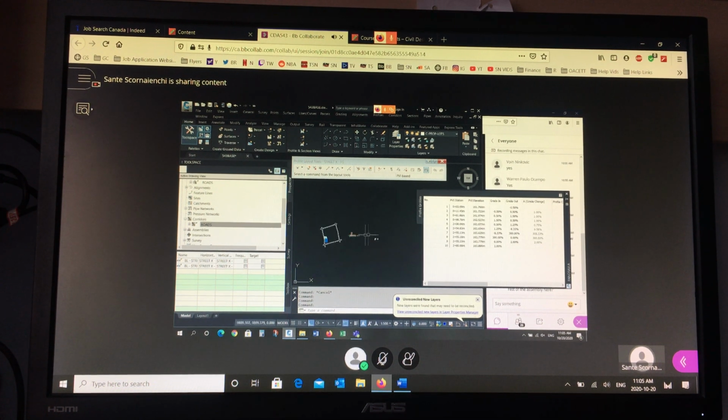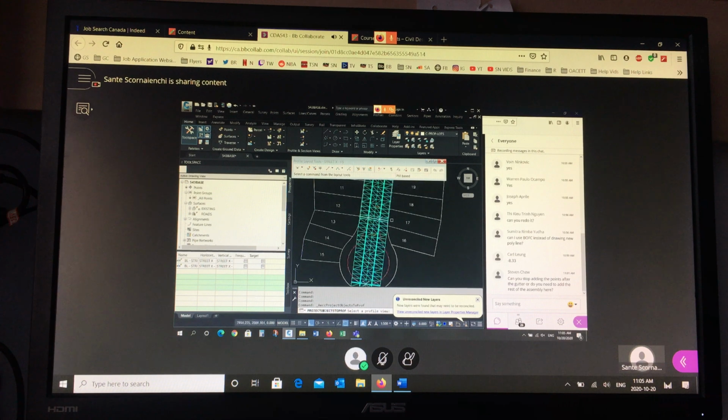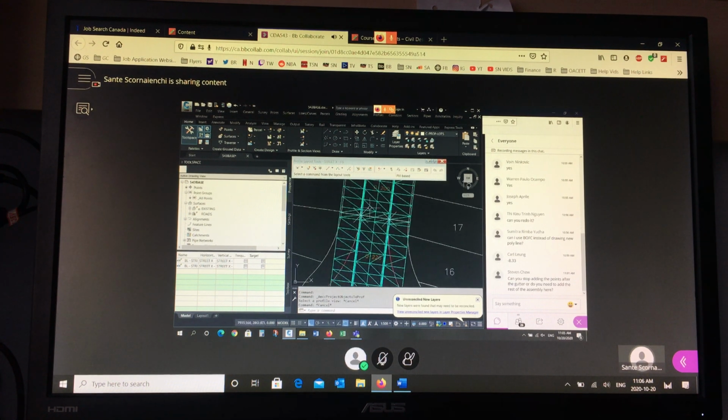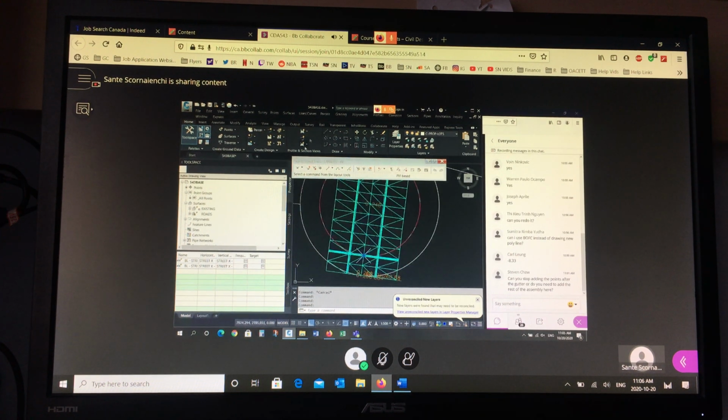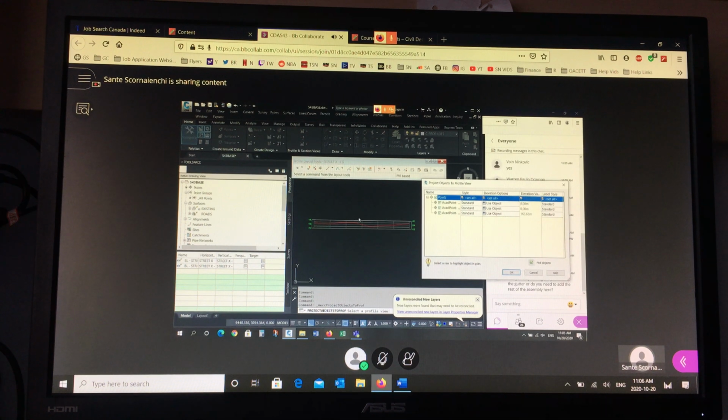So what we do is we project them to the profile. Let's get rid of this. Project them to the profile. So we go to this button here, profiles, project objects to the profile view. We pick the grid. I've already selected the points, so you can pre-select, 1, 2, 3. If you don't pre-select, you have to select them after you start the command. So I'm going to project those to this grid here, and I should get 1 on this end, 1 in the middle, 1 on this end.